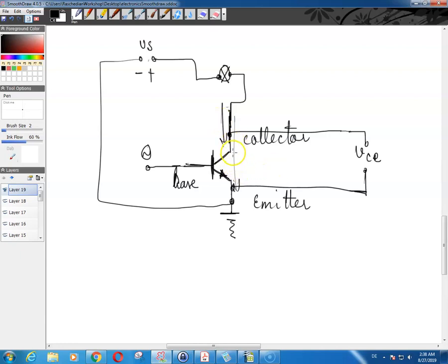And if, for example, all that you want to do is turn on some microcontroller chip or something that draws current in the range of a few milliamps or so, then you don't need a gigantic transistor with a whole lot of heatsink and all of those things, because then the emitter junction of the transistor is not going to have to dissipate that much heat, and so you don't need the heatsink anymore.